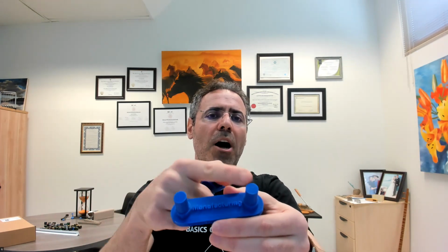And another thing that I advise, the center to center of these two, based on the calculation that we did for the example that we did was 84, but if I want to 3D print it, I make this center to center maybe 85 millimeters. This is just for the tolerance, making sure that these two gears work smoothly together. And like always, maybe you need to do some trial and error, which is the nature of learning. Good luck, and I hope you have some fun with this project.